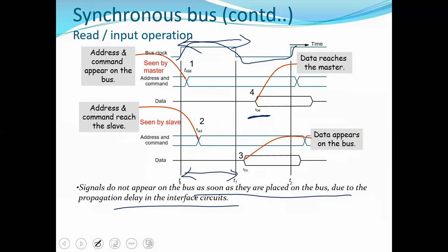This must be the longest width required in the system, so all the devices slow down. A hard disk, which is faster at putting the data, must also wait until T1 is reached, that is, half a clock pulse is complete, before it can start putting the data.